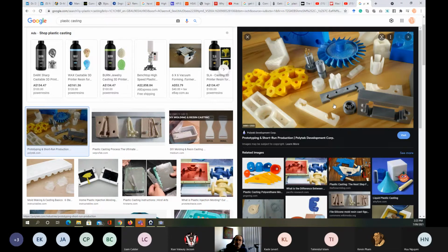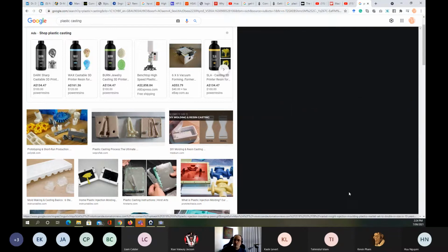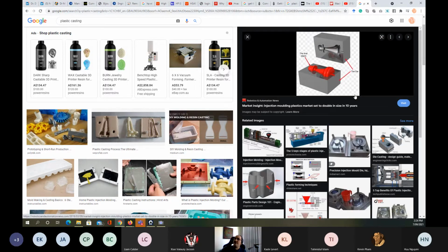We're going to have something we'll discuss in the major project, which is going to be the gear pump. So they have to do multiple machining operations, and they need to do some plastic casting operation to make the parts. They make the mold, they fill the plastic, and they can have the part directly. No time for the machining. The casting operation is not going to be costly. The only thing we're going to spend the time on is making the mold, and that's it. That's another example.